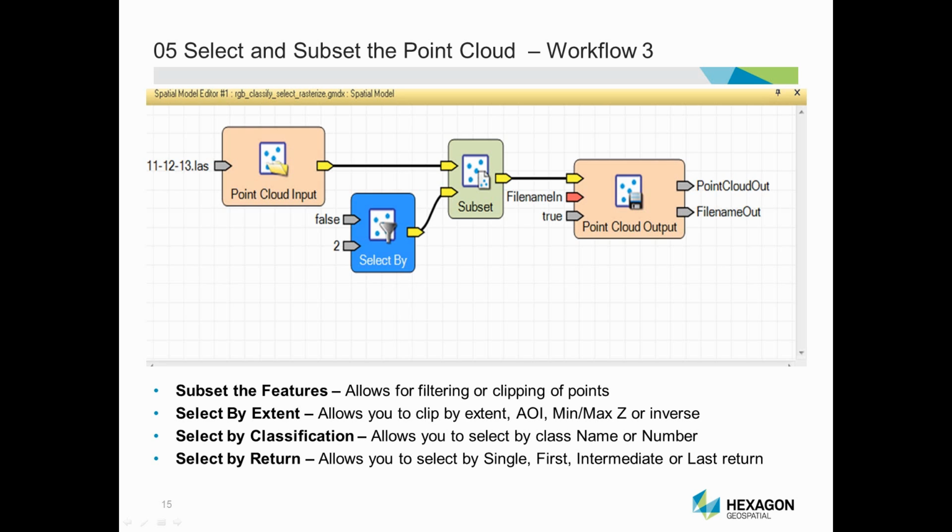You can select by return also. If you have a LIDAR sensor format LAS file that has a bunch of different returns, you can select based on single, first, last, intermediate return for a more accurate output option.